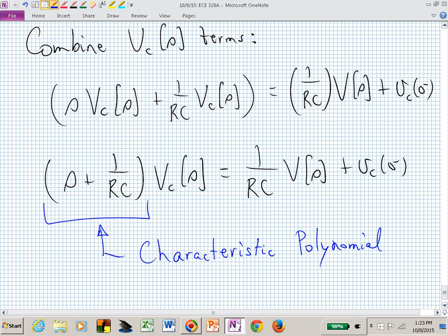What kind of modes does it have just naturally? The response is going to contain not only the modes due to the system itself that it naturally contains, but it's also going to be influenced by the input voltage waveform that we're applying, and that will come in as the capital V of s. We'll just Laplace transform that little v of t.